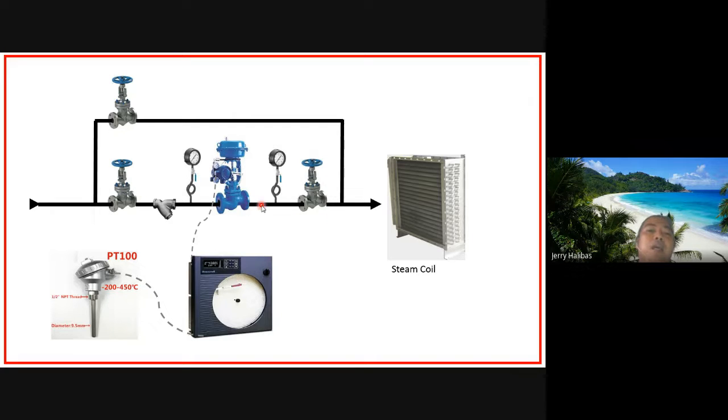So these two valves are bypass valves. You close them because it is very hot before you pull out the component. By the way, these are ball valves. Without a ball valve, you cannot test whether your pressure gauge is broken. So take note, since it vibrates, a liquid-filled type is better, not the dry type, because with steam it reaches areas you cannot read. Then, of course, the smart valve positioner is connected by 4 to 20 mA to your temperature controller.